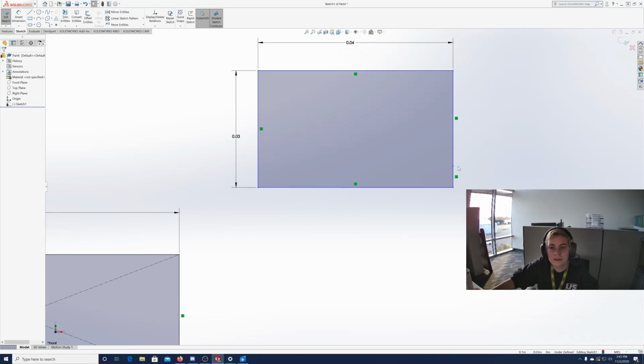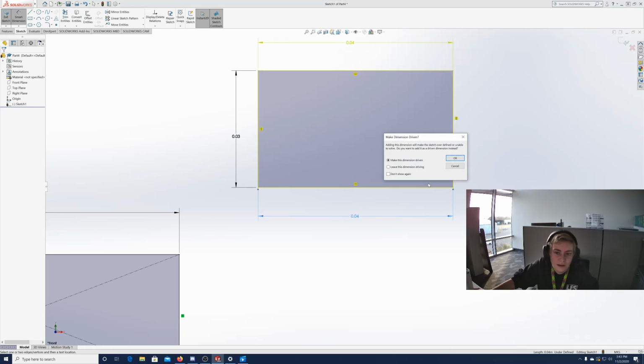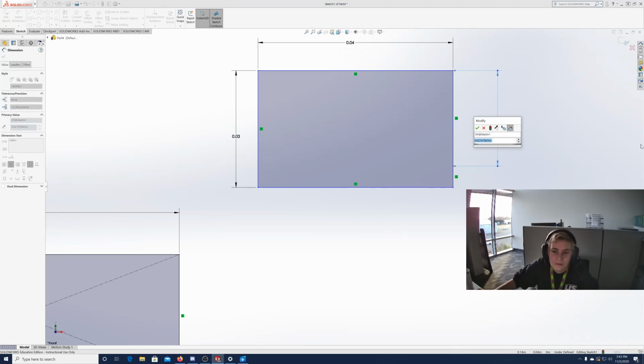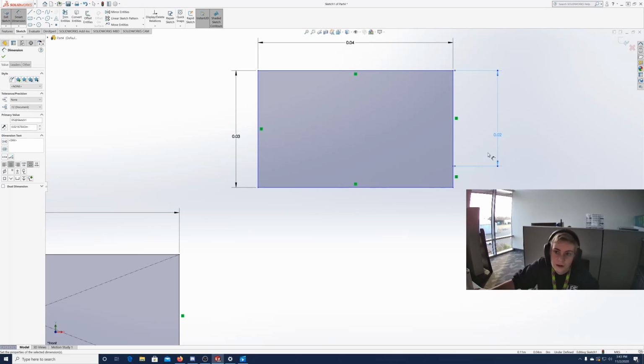You have these two segments of line here, and that's going to cause problems for you down the road. Because say you keep dimensioning, and you're like, okay, so what's missing now? Well, that's going to make it over-defined. What if I dimension this? Okay, for some reason, that's not grabbing the whole line, it's getting that piece. And you can't figure it out. It's because you have this weird segment here.